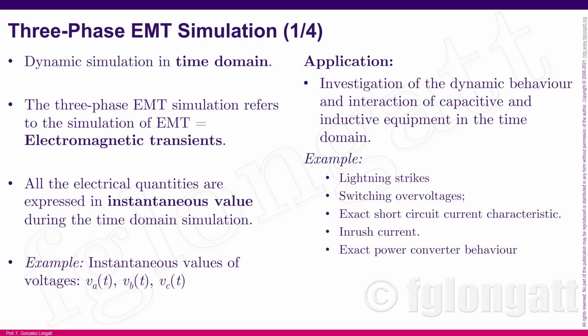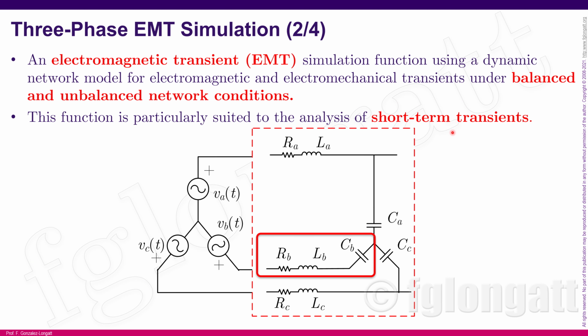And the best way to get the full representation of the short circuit current is using time domain simulation, specifically the three-phase EMT simulation. Also, other interesting phenomena like inrush current or motor starting are well suited to this kind of EMT simulation. What is the bad news? Well, EMT simulations require a very small time step for the integration, okay? It can be computationally expensive.